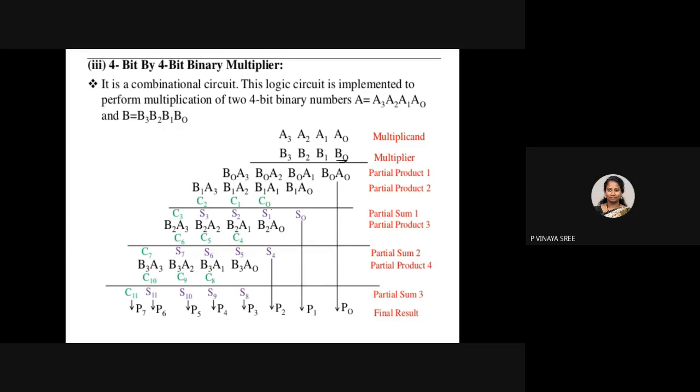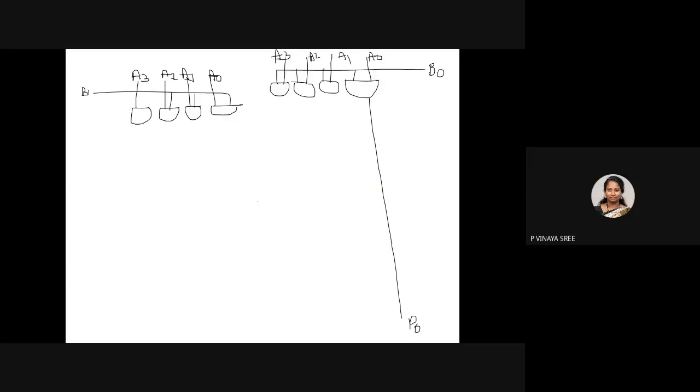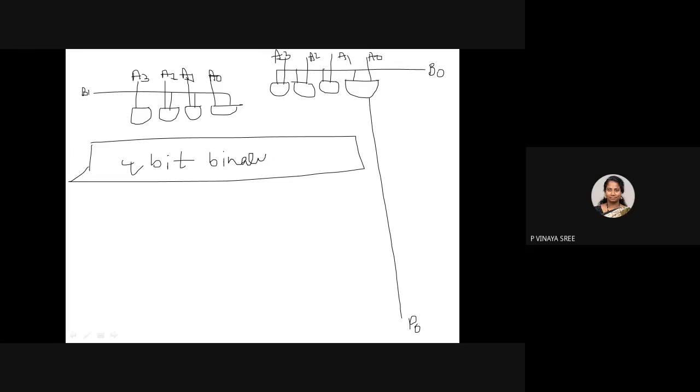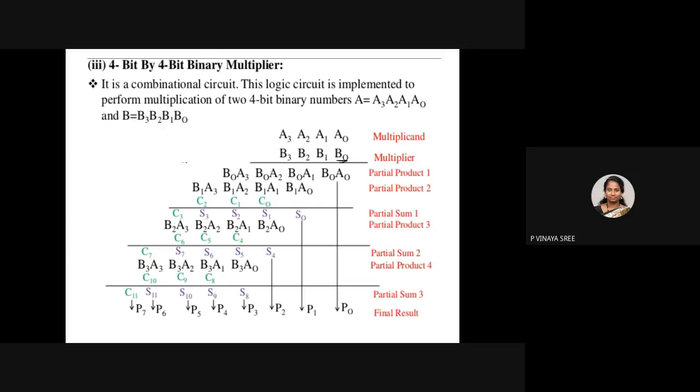This we are giving to a 4-bit binary adder. In this case, you have 4 bits, but in this case, you have 3. The other bit, where will you add it, right side or left side? Left side. At the most significant bit position, you will add 0, so that this part will be completed.